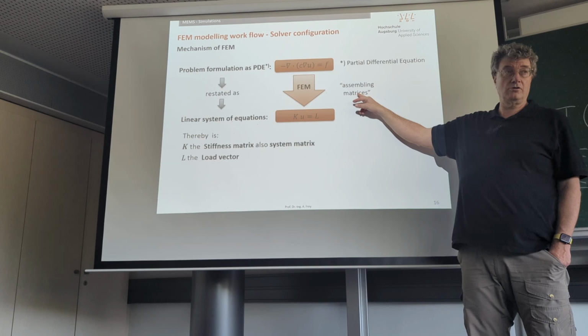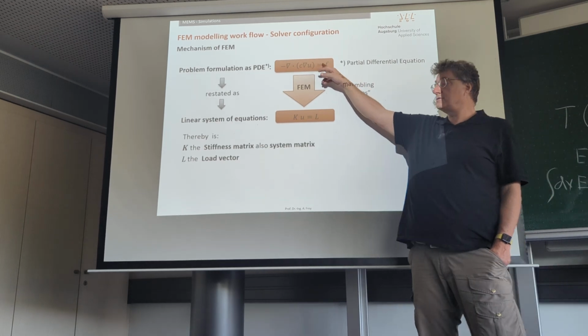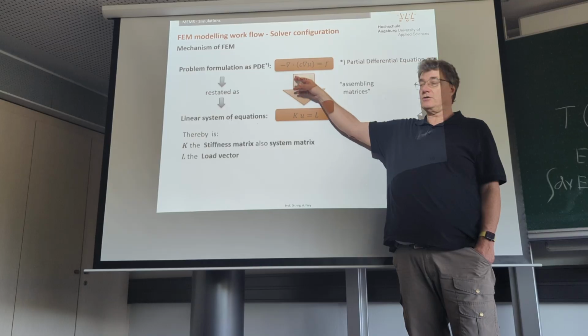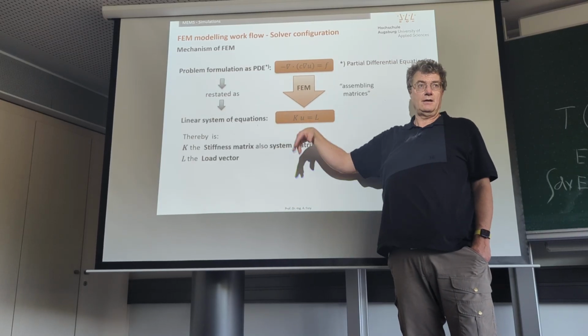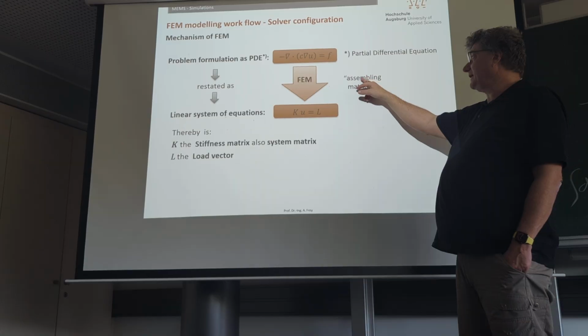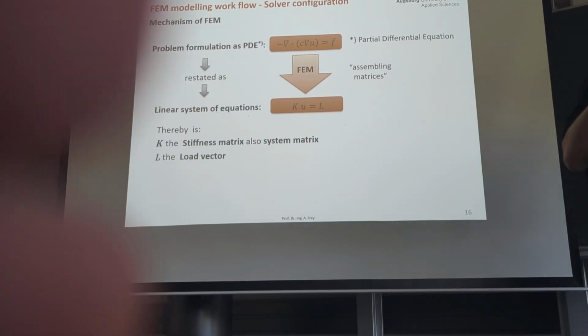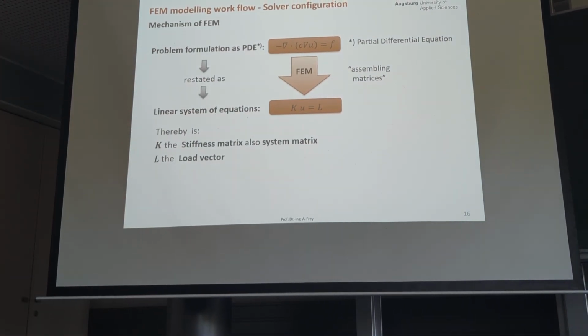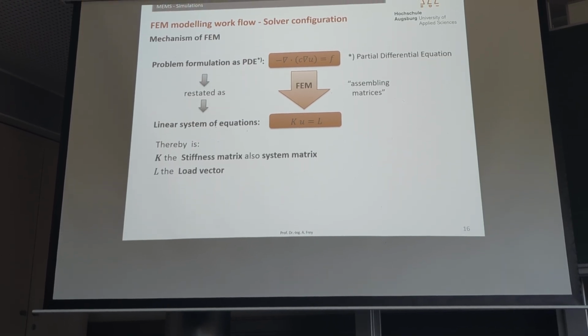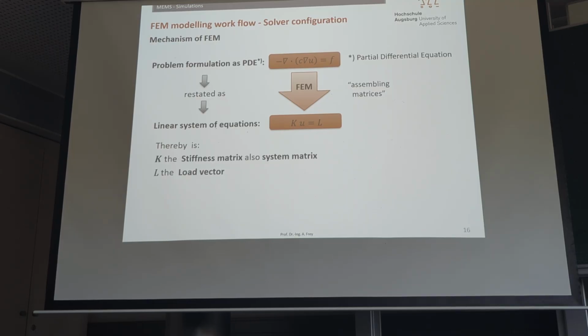So then you know COMSOL is busy transforming the partial differential equation or combined partial differential equations into a lot of equations, basically extracting matrices. That's why it tells you assembling matrices. If you have very small models, it goes so quickly that you cannot see that term. But if you have a large model, you would see it. It takes a while. That's the first thing. At least this is the way COMSOL is working.